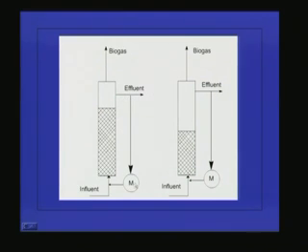And in this system, recirculation of effluent is most of the time a must. The reason is that the influent may not have enough velocity to fluidize the bed, depending upon the bed material, because if it is sand particles, you know the specific gravity is very high. So we need a very high upflow velocity to fluidize the material. Most of the time we recirculate the treated effluent to give enough upward velocity here.